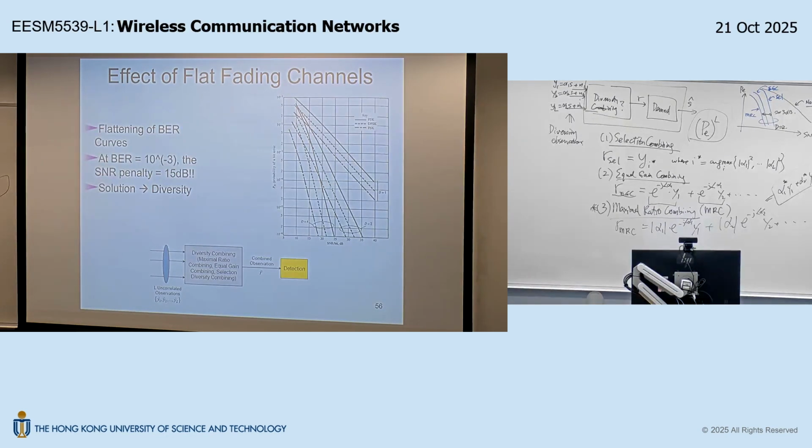Is that okay? So at the end of T2, the baseband will be able to get alpha 1 hat and alpha 2 hat simultaneously. And from this point onwards, I will be able to know which one is the most reliable path. Suppose alpha 1 is most reliable, okay? Alpha 1 hat magnitude is larger than alpha 2 hat magnitude. Then from T2 onwards, I have the switch in position 1.